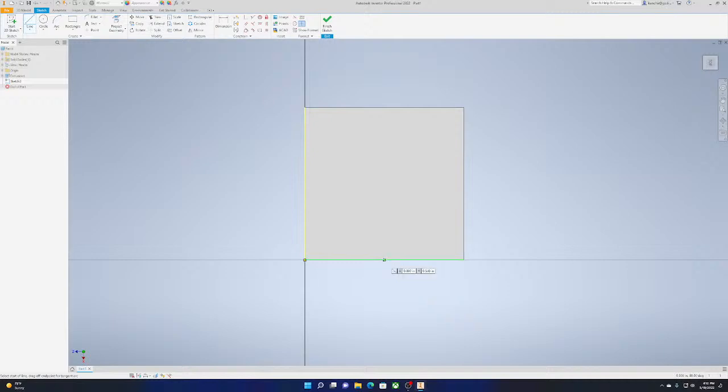You can see there's a line. I can then go up, and I already know it's going to be 0.5, so I can just type in 0.5 and hit enter. And you can see with the line tool, it'll ask, do you want to continue the line? We don't really need to. We can hit escape. Then you can click on the circle tool. We now have an origin, and you can see how far we want to go out. So this is an inch, and that won't be as helpful. So let's go 0.75. That's good.